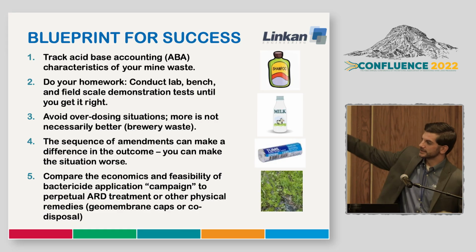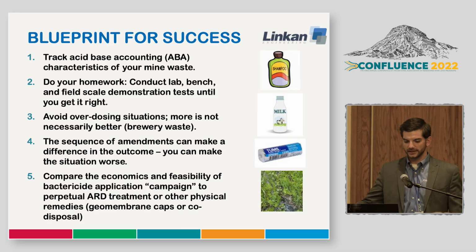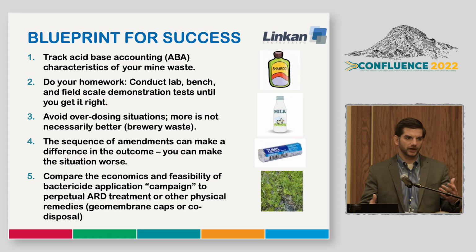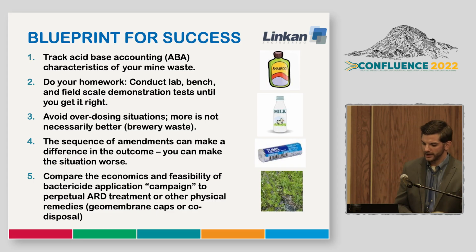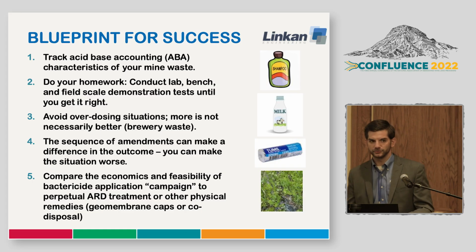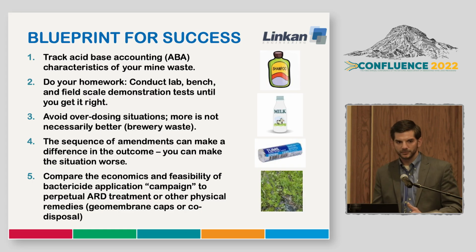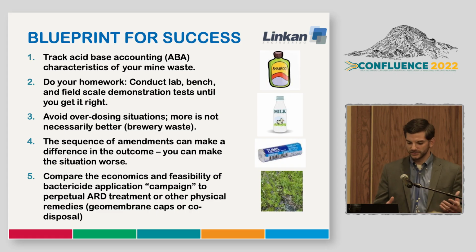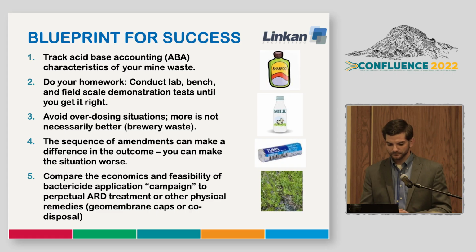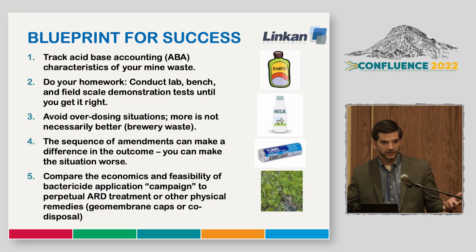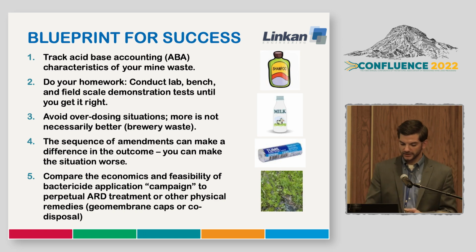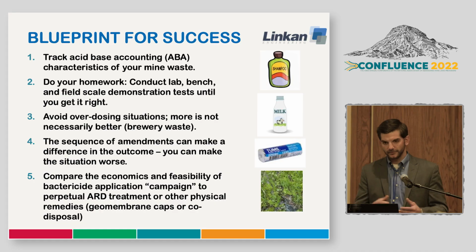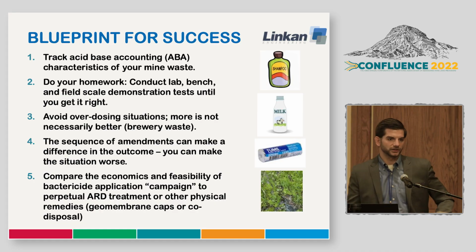So again, this is kind of the track that Lincoln takes and that I would suggest to you. Do your homework, figure out the acid-base accounting, how much pyrite you have, conduct the lab, the bench, the pilot scale studies. It is time intensive, it does cost money, but the benefit in the long term is invaluable. And then obviously look at the economics, right? We want to assess the feasibility of the bactericide application versus the perpetual ARD treatment.